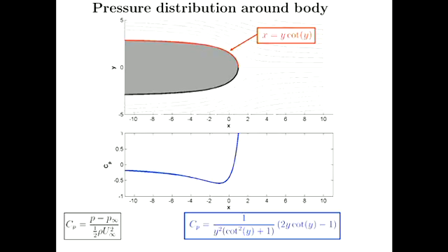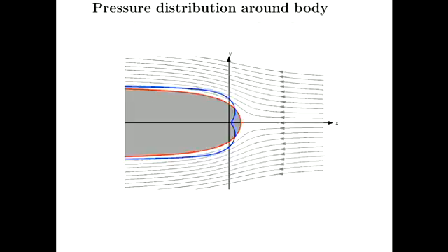You'd have found the xy coordinates for that separatrix using one of these Euler or RK4 codes that you're currently writing. Then you could have evaluated u and v at all of those coordinates, pushed those numerical values into the equation for the pressure coefficient, and immediately plotted that blue curve without all of that agonizing algebra.